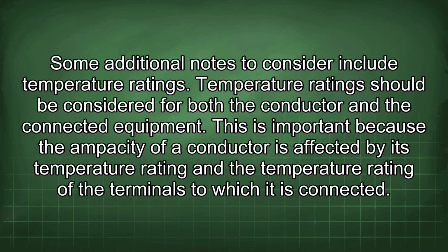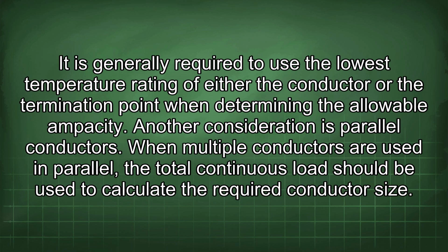Some additional notes to consider include temperature ratings. Temperature ratings should be considered for both the conductor and the connected equipment. This is important because the ampacity of a conductor is affected by its temperature rating and the temperature rating of the terminals to which it is connected. It is generally required to use the lowest temperature rating of either the conductor or the termination point when determining the allowable ampacity.